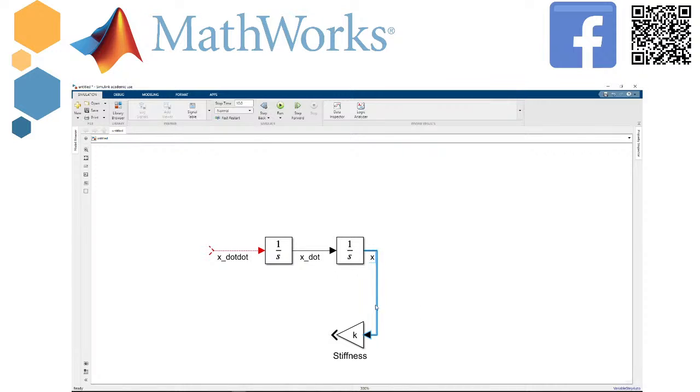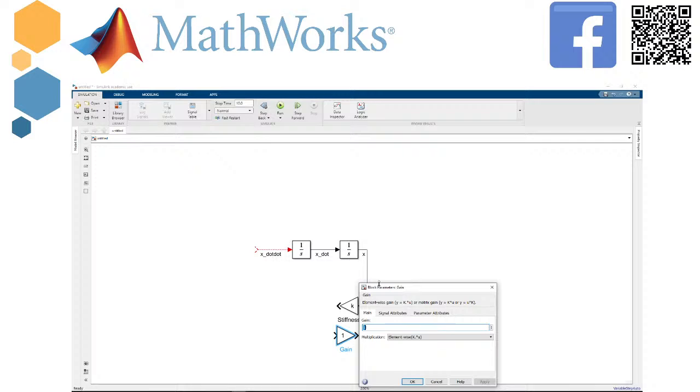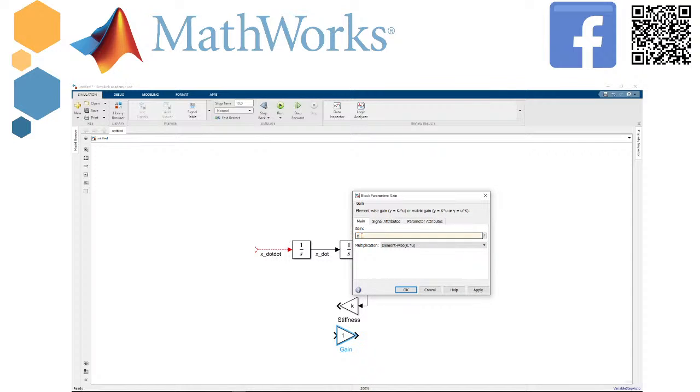For x dot, x dot is multiplied by the damping coefficient. So I can write gain again, click on it, and create a new variable called c. Of course, it's not in the workspace of MATLAB, so I need to create it, and it will be suggested here.